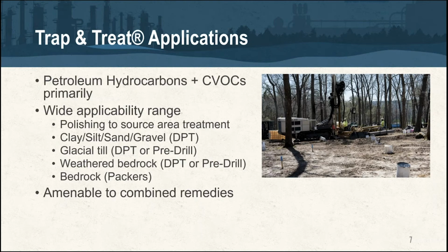And then lastly, as I mentioned before, we do some bedrock work. That's not going to be the focus of this presentation; that's got its own breakout webinar. But there we're using straddle packers to isolate fractures that have been identified to contain contamination, to be able to pressure inject the slurries.